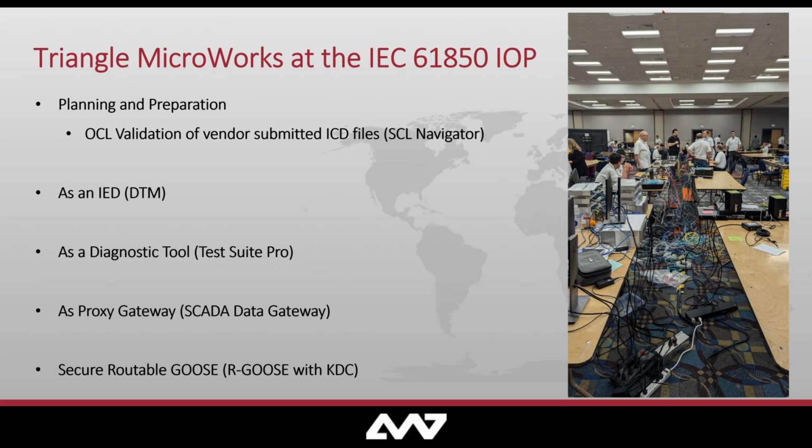The validation was done using OCL, or Object Constraint Language rules. These particular rules were written by a task force within Working Group 10 and applied using the open source RiseClipse engine. RiseClipse is incorporated into a couple different tools, one of which is our own SCL Navigator, which is a tool for both editing and creating ICD files, as well as other sorts of SCL files.